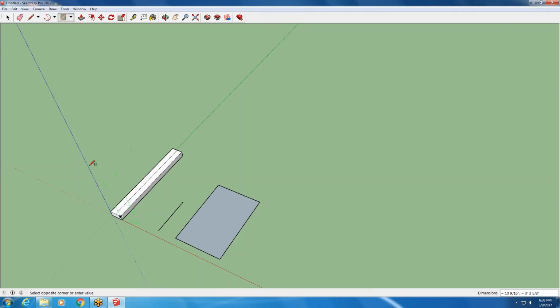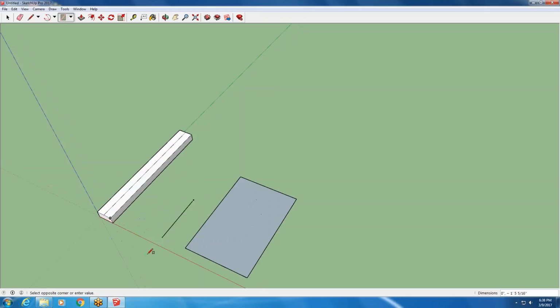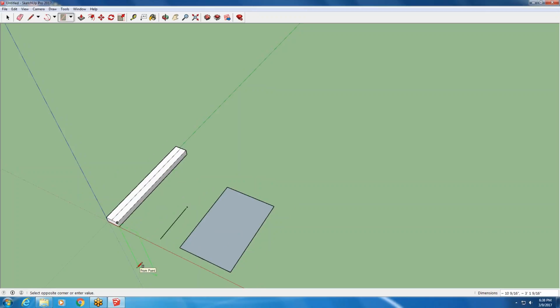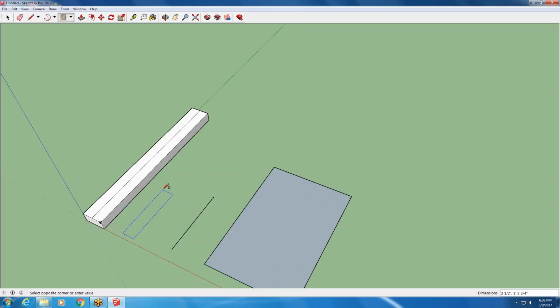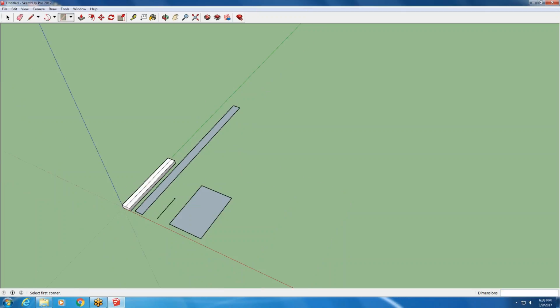Look how crazy that got, because I started drawing it too zoomed out, and it might go down or up or over. So zoom in and be on your right axes. If I come in here and then I do 6-inch, 10 foot, I could have a really nice wall done in no time instead of doing a bunch of lines.